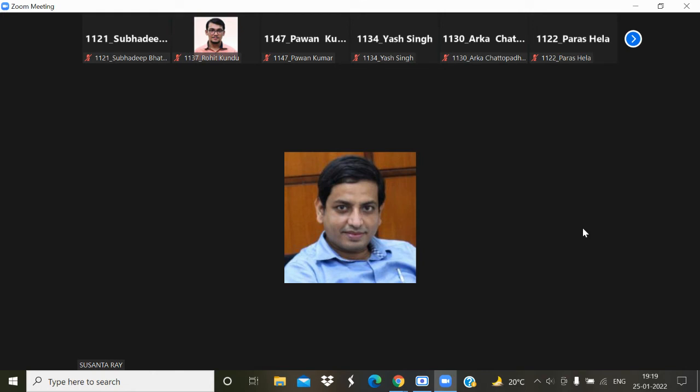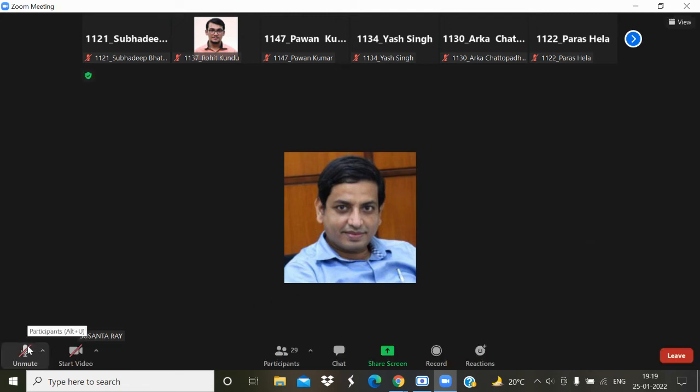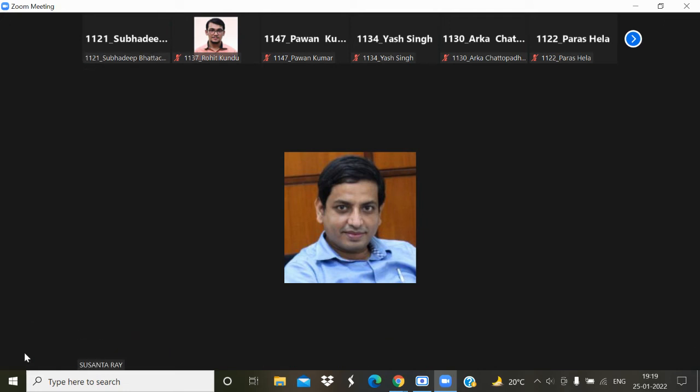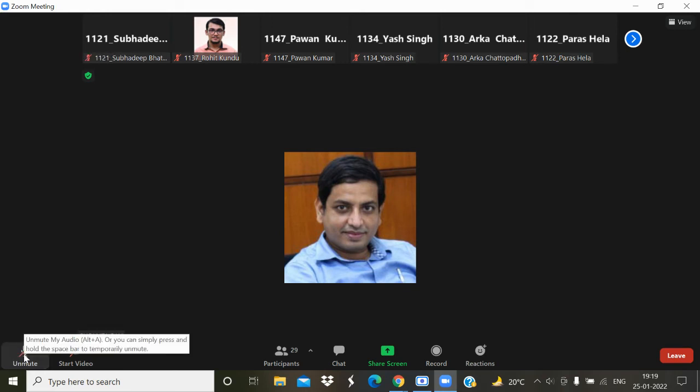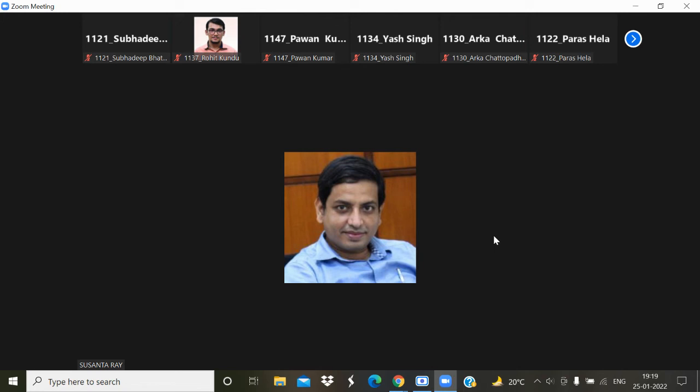No, one more thing will be there. Last class I discussed in detail. What is that? Our AC machine, that would come. Yes, the winding factor. So you just write down the expression of C0, that is 11 into Kw into B average into AC into 10 to the minus 3.